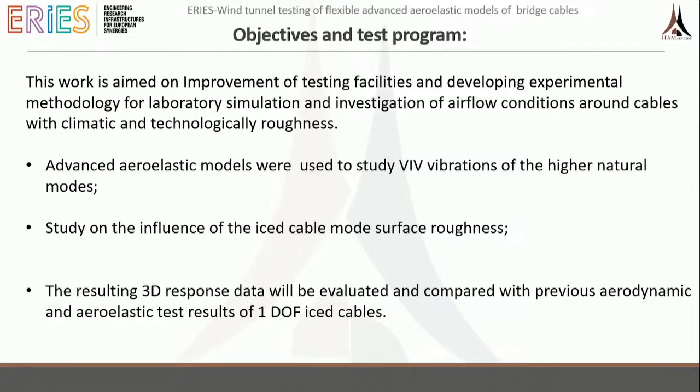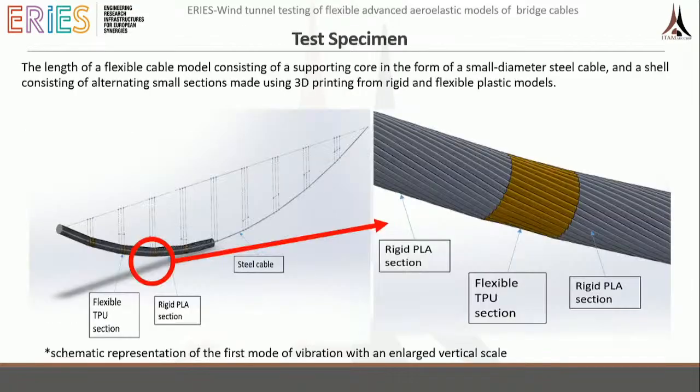So advanced aeroelastic models were used to study VIV vibration of the higher natural modes. We also studied the influence of the accretion on the cable, or, as I said, any modification of surface roughness. And the 3D data will be soon available also for any other researcher among us. So this is what the ERIES project or ERIES idea is serving for.